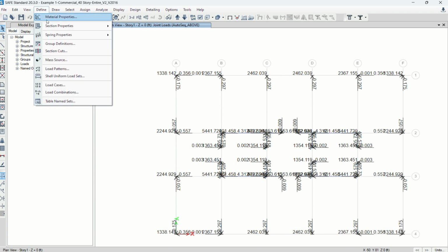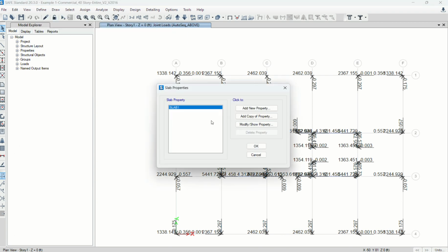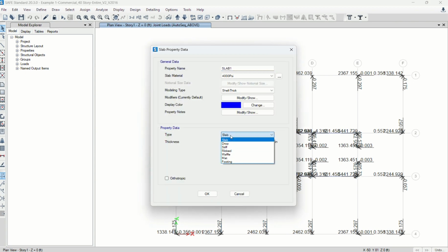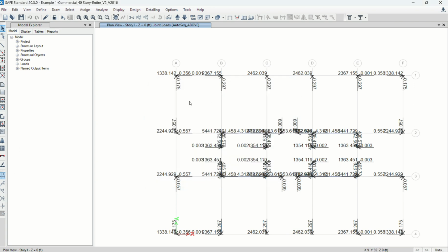So also I'm going to create the slab. This time it is a mat, right? Defaults, I'm going to change the default to mat type. Maybe we're going to assume that this is an 8 foot thick mat, 96 inches. So let's say 96 mat. I'm going to use the 5,000. This is just an initial trial.